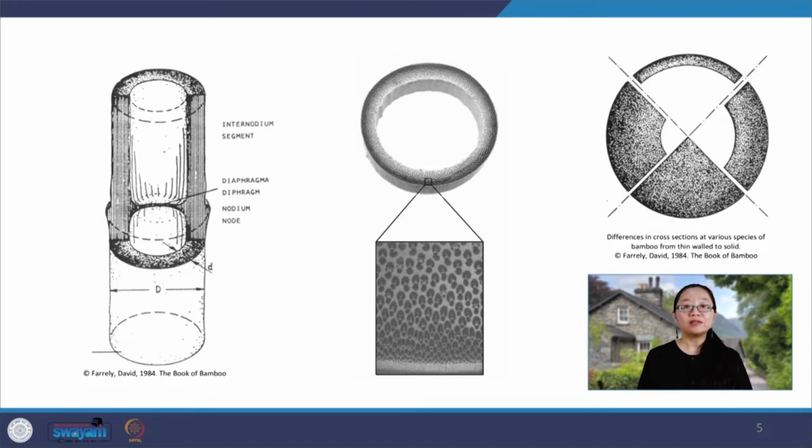Depending on the species, the thicker culms have moderate elasticity, while the thinner ones have more elasticity and considerable strength. The reason for this elasticity is a conical profile, bigger in the ground and smaller towards the top. This character can create a variety of forms, but at the same time, due to these changes in the diameter and the thickness of the bamboo stem along its length, in addition to the stem not growing totally straight, precision in construction is difficult to obtain.